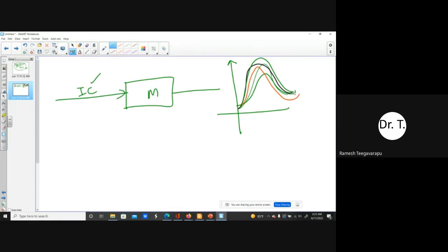If you are a manager of a particular water agency, or a reservoir manager or a dam operator, then you look at this and see that most of the ensembles are falling here. You can actually calculate the probability, because you know the number of ensembles compared to the total ensembles. You can say what is the probability of this value occurring, an average value of that.